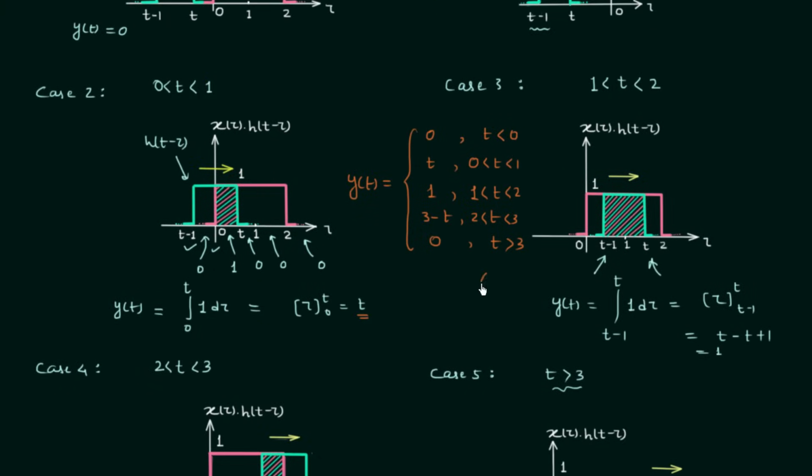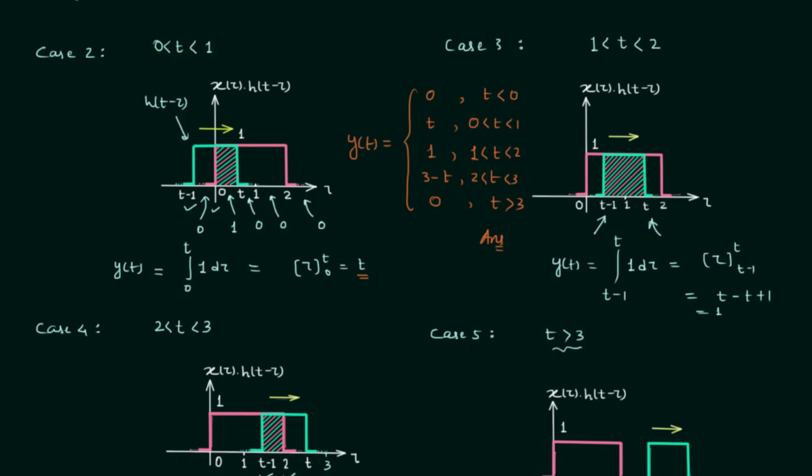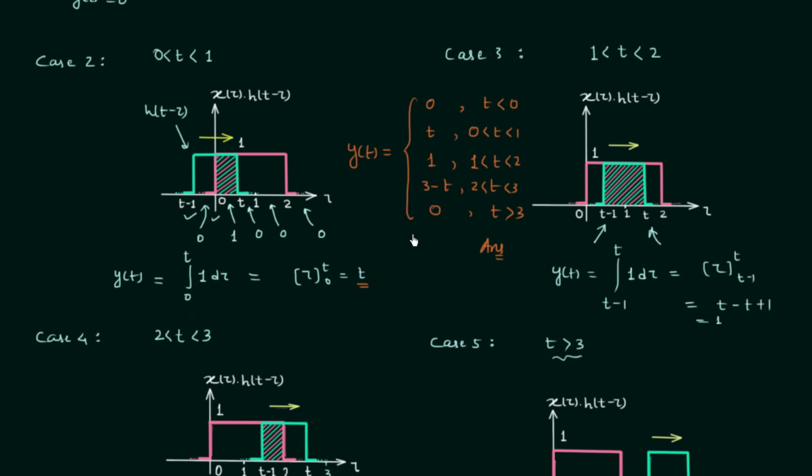You can write this as your answer, and if you want to find out the waveform, you can easily plot it using this definition, and you will see the waveform of the output is trapezoidal because we have two rectangular pulses with unequal width. So whenever you have two rectangular pulses with unequal width, you will get the trapezoidal waveform as the output, and when you convolve the equal width rectangular pulses, you will get the output as a triangular signal. So this is one important point, because sometimes while choosing the 4 options given, you can use these small properties.